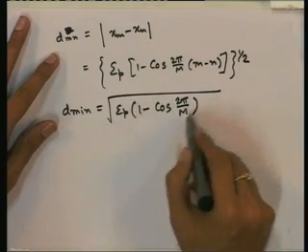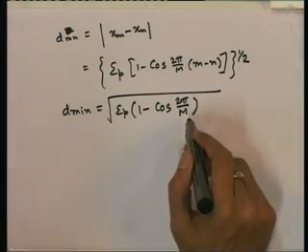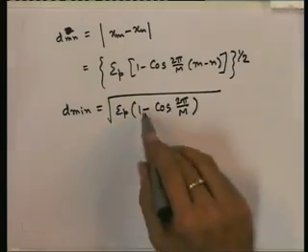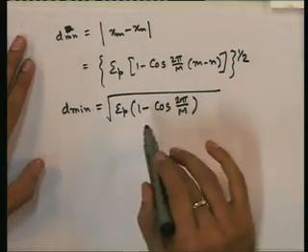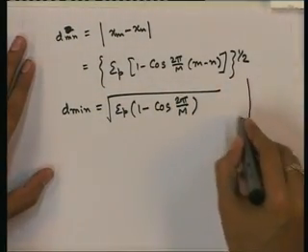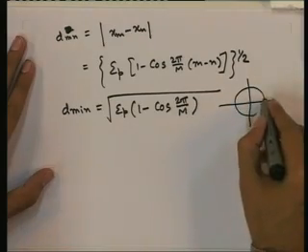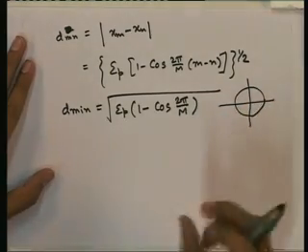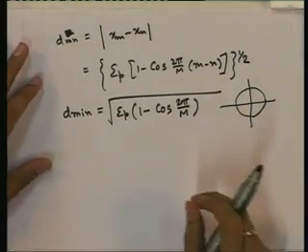So, as a result, this quantity decreases. So, as we increase M, this minimum distance decreases, and we can also see that from the figure: we have to fit more points on the circle, then we have to put them closer, that is the only way. So, 8 PSK will have smaller minimum distance than 4 PSK, 16 PSK will have smaller minimum distance than 8 PSK, and so on.